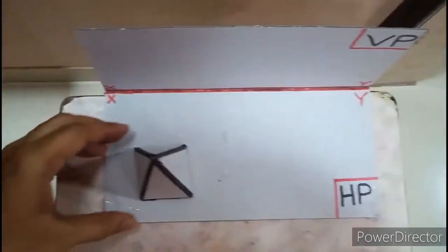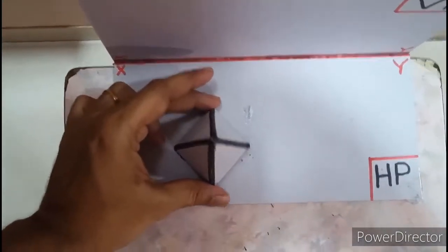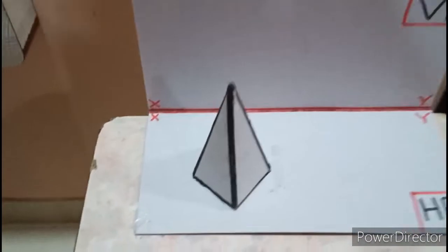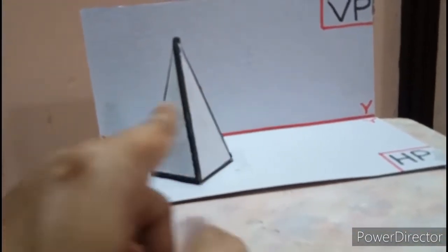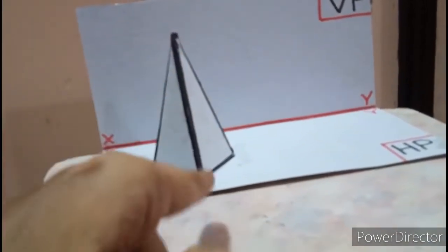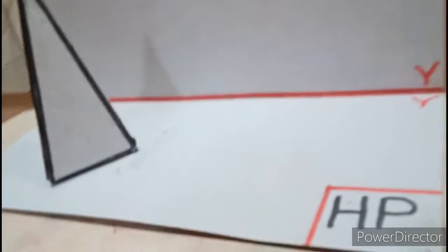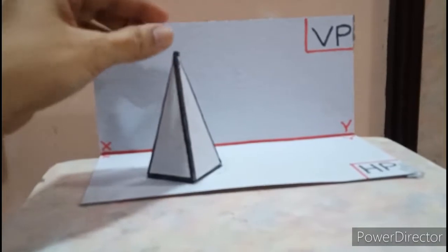But if I change the orientation and draw the square like this, on the right side I'll place a corner. So if you look at the front view, instead of a plain surface, you will find two triangular faces, which are separated by one vertical slant edge. Can you make out? There are two triangular faces. Now on the right side, you will find there is a corner. See, this is the corner here. There is a corner on this side.